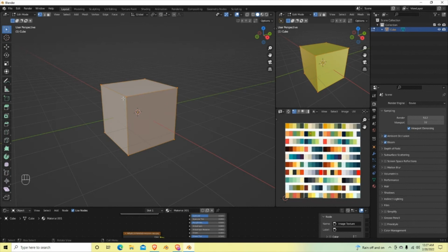Now, also, let's show you what else is cool about that. Right now, we're in the vertices mode of edit, okay? And you control that with the number 1 on the keyboard. If you hit number 2, it goes to the edges. So now I can select individual edges all around the cube. And if I hit 3, I can hit the faces. So now I can select certain faces of the cube, okay? So again, 1 is for vertices, and I can just select each individual vertex that way. 2 is for edges. 3 is for faces, okay?